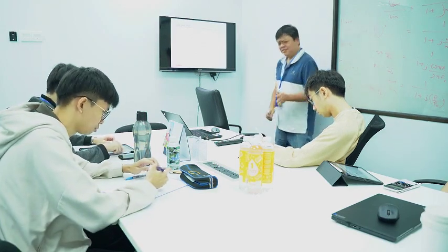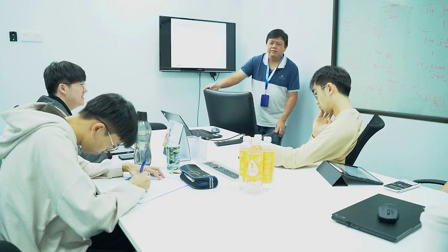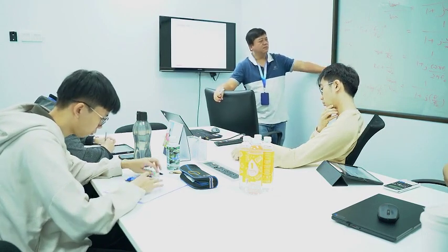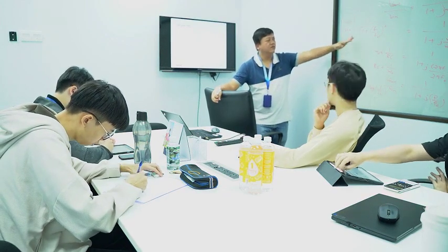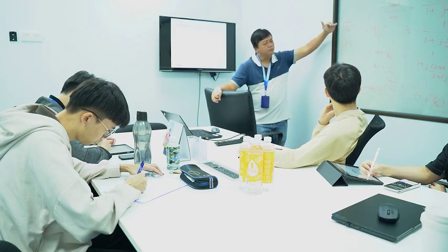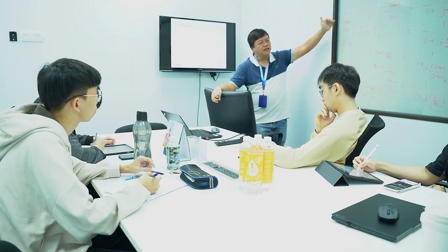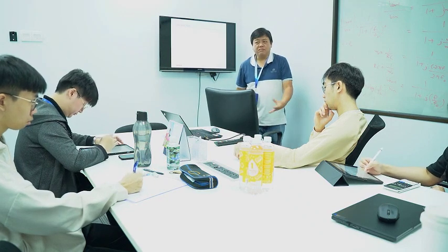It's not like people simply put the minus 3 dB. It's because it follows the formula. You look at the formula, you can follow me. It's exactly from f equal to f0. Your input frequency equals your cutoff frequency f0, and then your gain is minus 3 dB. That means at the particular cutoff frequency you measure, your gain will drop by minus 3 dB. This is the reason why we look at minus 3 dB for cutoff frequency.